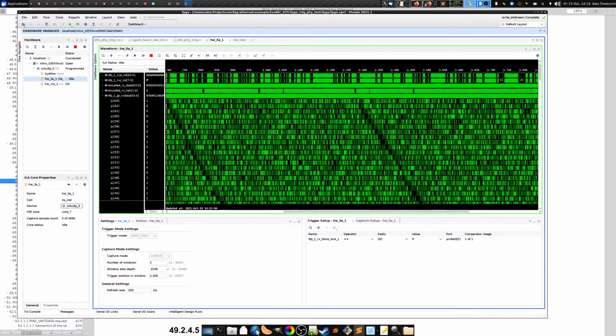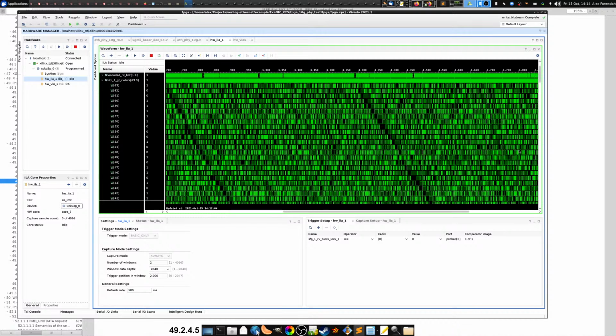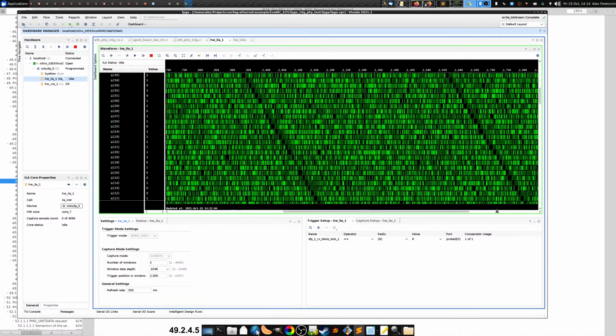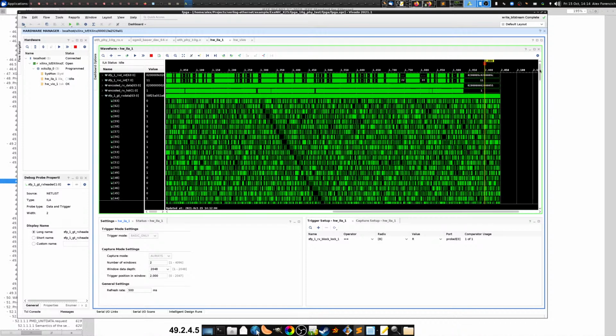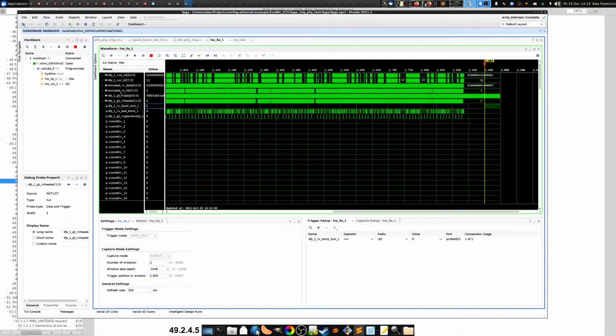So here's your sync header, and it's being shifted and shifted and shifted and shifted and shifted, and eventually it gets down to the bottom where it ends up getting moved over into the GTRX header. At that point, you have the correct alignment, and it locks. So yeah, there you go. That's what it looks like while the block lock routine is running and it's trying to lock onto the data.